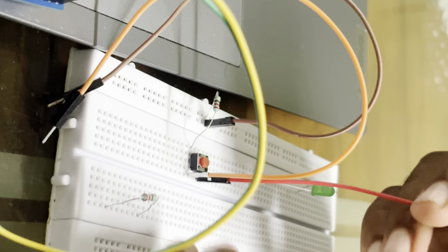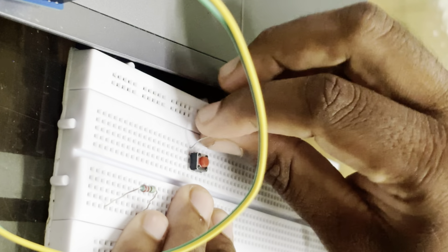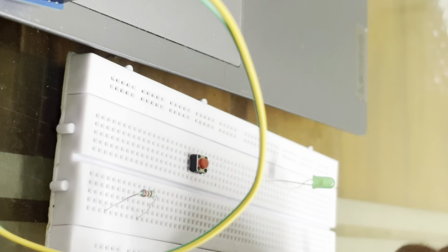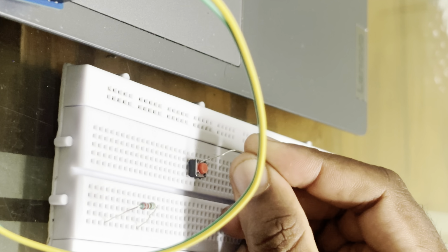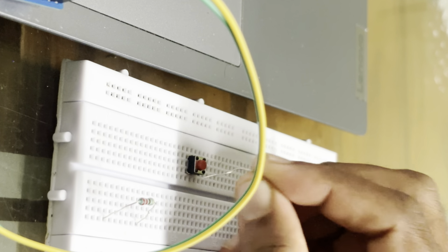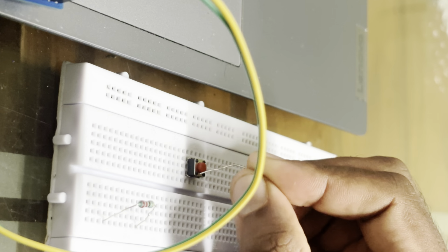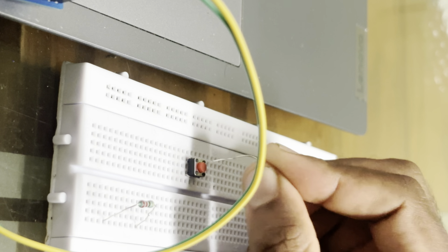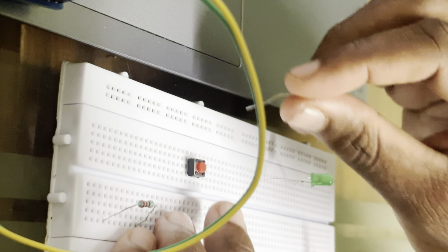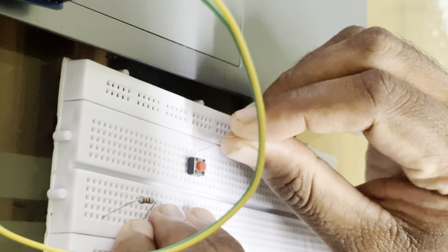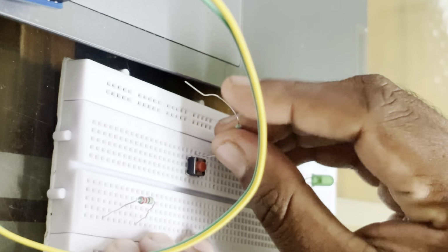Look here, I am going to wire this button. First removing all this, then this is the button itself. For the button, this and these are same connections. These both are same connection. They are different. Now first we are giving a 220 ohm resistor from one side of the button to the ground.